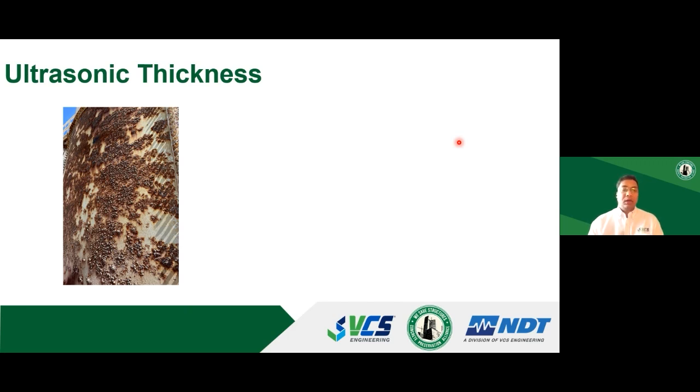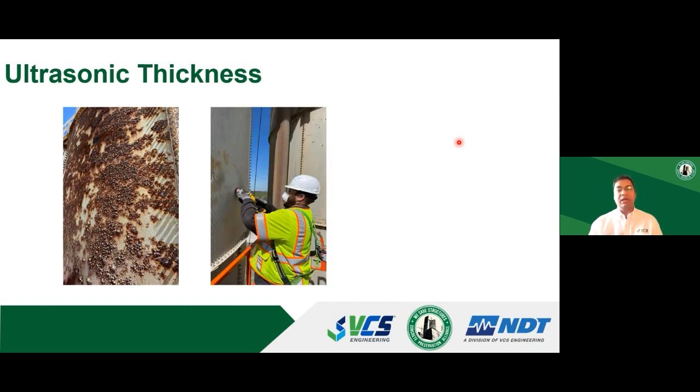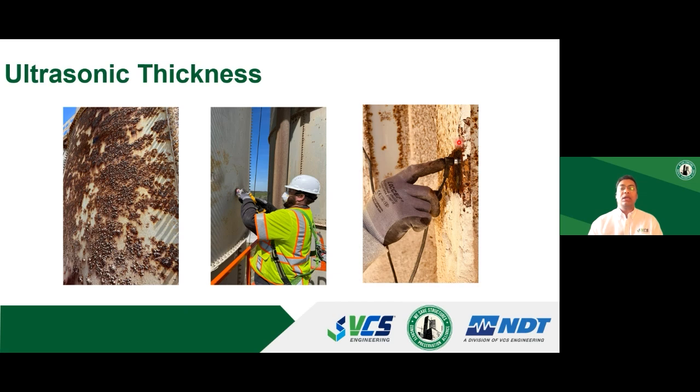So it was a coated steel. You have severe deposits of rust. We cleaned the concrete, we cleaned the steel surface using a metal grinder, and then we did the section loss measurements on the silo, and we do this test often. Now, in addition to ultrasonic thickness testing, we have run a similar kind of test.